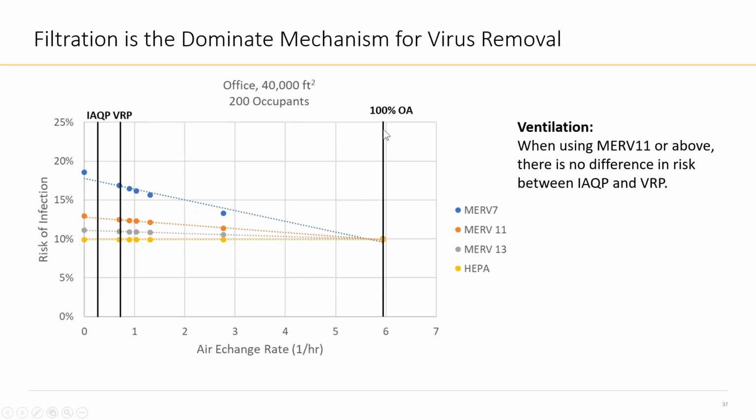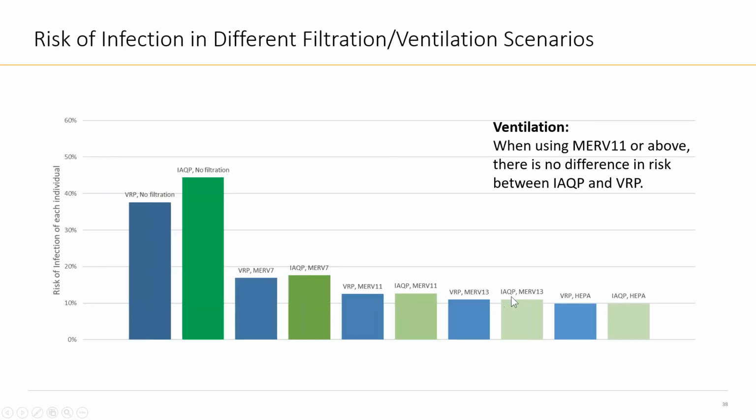And I would argue, first, that it's not feasible today, in the summer or in the winter. It will not make sense to open your outside air if you're not in economizer mode, because you're not going to be able to maintain your comfort conditions. So the premise is that if you use MERV 11 or more, or higher particulate filtration if you can, you'd be in very good shape. In case the virus is airborne and goes to your filters, you're probably going to be able to remove it. And of course, different MERV 11 filters have different efficiency.